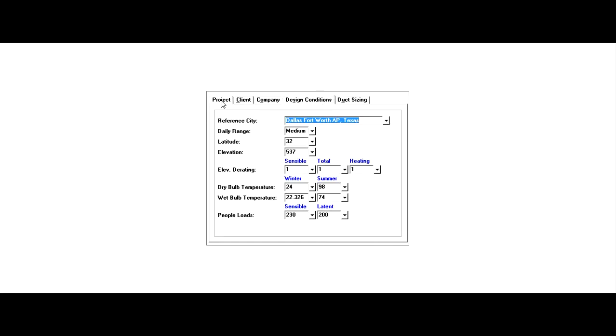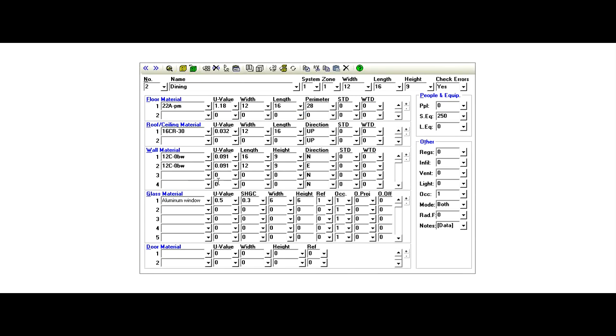energy code. So it's still the same 2900 square foot house I've been using in all my videos. But now we're going to use the 2009 energy code requirement for the Dallas-Fort Worth area. So we have a vented attic and duct in the attic. What did the 2009 code require? Well, as far as the floor, there was no specific requirement for this region, so we're still going to use the same concrete slab we've been using all along.